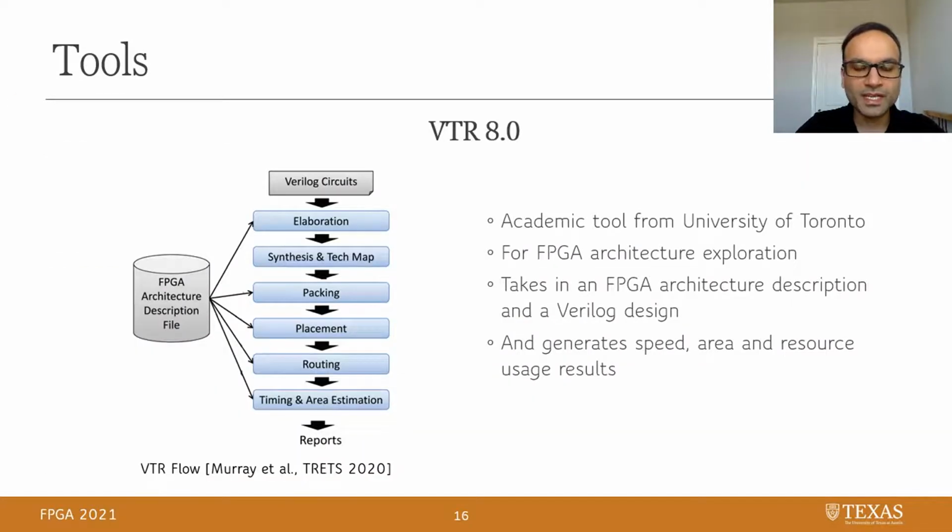We used many tools for our evaluation, the most important ones being VTR and Coffee. VTR is an academic tool from the University of Toronto for FPGA architecture exploration. It takes in an FPGA architecture description file and a Verilog design and performs synthesis, placement, and routing on that design for that FPGA and generates area and timing reports.